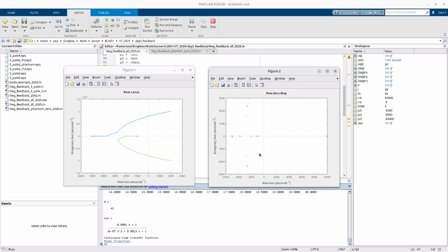So two poles with a zero. The right-hand zero is located here, and then we have two poles. Without the zero, the two poles split and go vertical, but in this case we see that the zero starts to attract the poles, and if the zero is on the right-hand side, it will start to deteriorate the stability of the system, because now the poles have crossed.